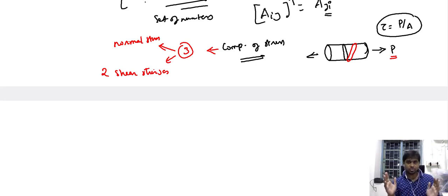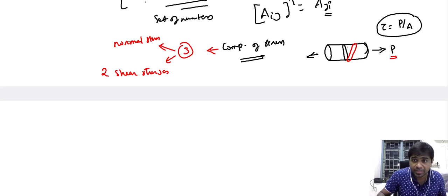So we are focusing on an inclined plane, and in that inclined plane we want to describe the mechanical condition that we are imposing. Now the stress, with reference to the inclined plane, cannot be described using just one scalar value. We cannot do it. We have to dissociate it into its components. So in order to describe the mechanical condition experienced by the red plane here, the inclined plane, we need to consider three components: one normal stress and two shear components.